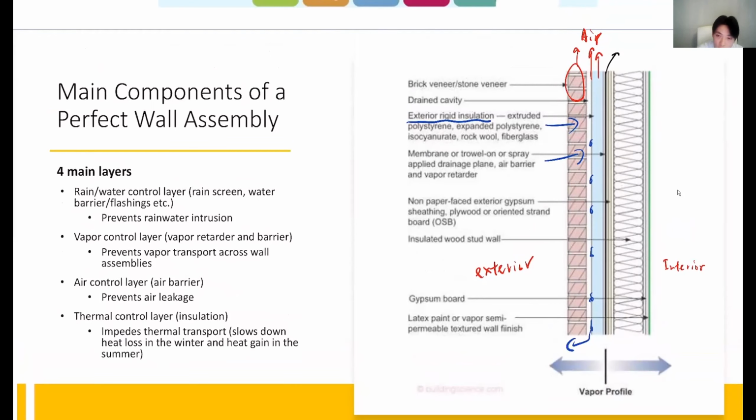Say you're really unfortunate, and the water gets through all those layers outside and gets to this layer. This layer is the absolute last control, right? We have to control this water, otherwise it gets into our insulation or our indoor space, which is going to cause a lot of problems, like degradation of the wall assembly and maybe mold growth.